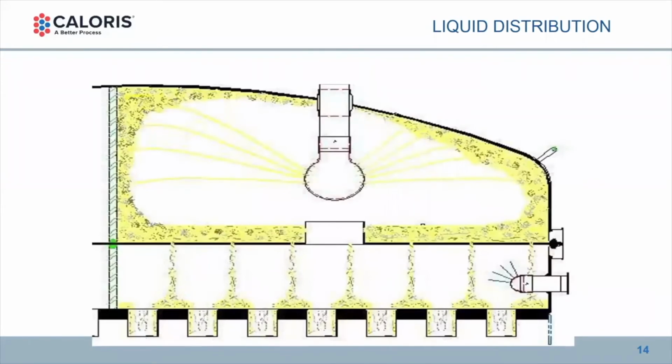There are variations of distribution, of course. Spray balls are used for that initial distribution of liquid and allowing it to degas and flash a little excess energy off to boiling temperature before you then distribute through a plate. We've rebuilt some evaporators where that distribution plate is not there. It's just a spray ball spraying product down onto the tubes.